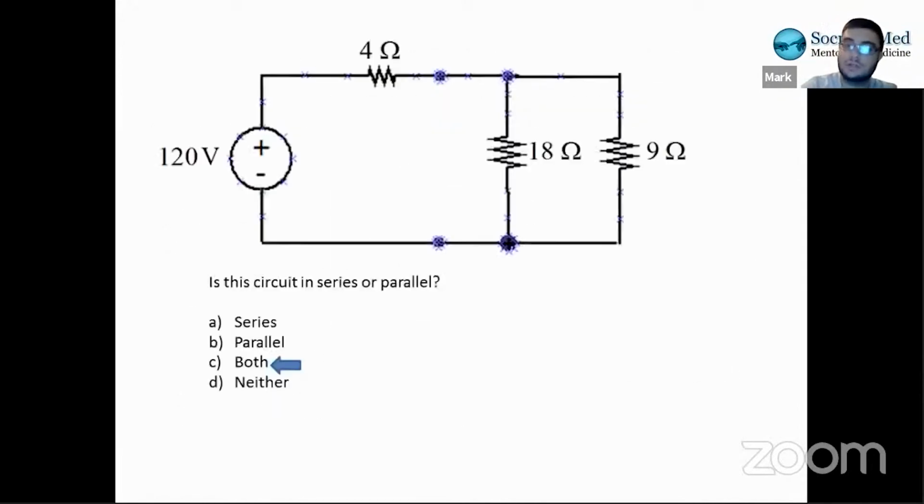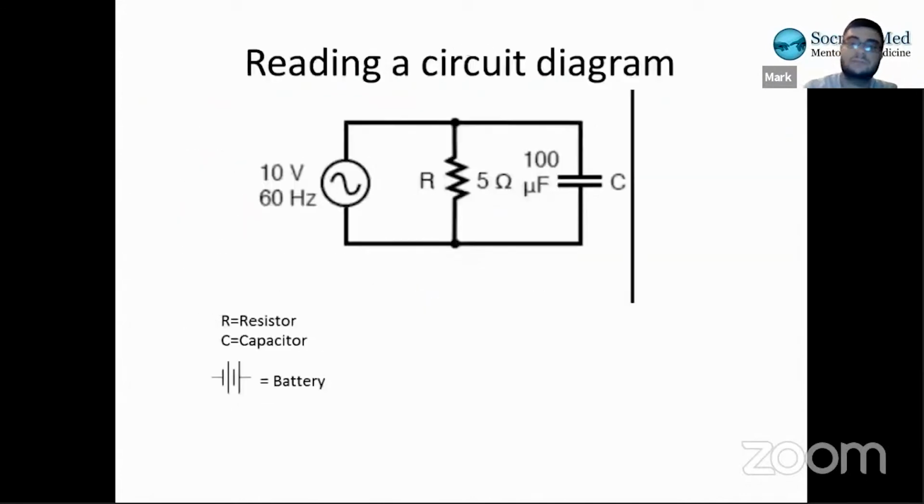And I want to actually go back to this. If this was a resistor, we know how to do resistance in parallel. We could find the current running through all of these. We have V, we have what the resistance is. How would we do it if we had a capacitor in here as well? Well, if it said this capacitor is fully charged, what that means is no current actually passes through it. So even though these two are in parallel, you can think of it as current only passing through this way.